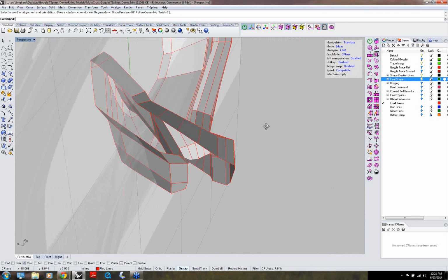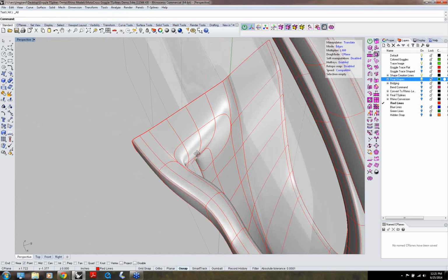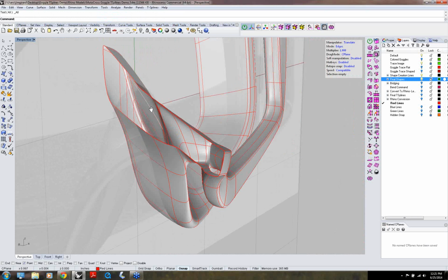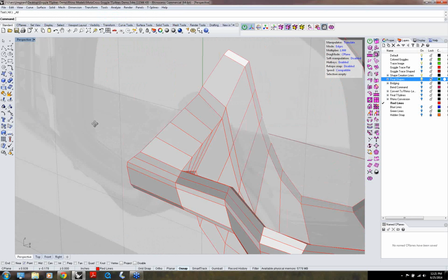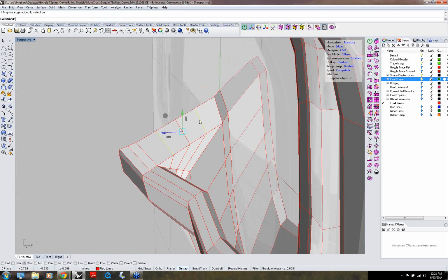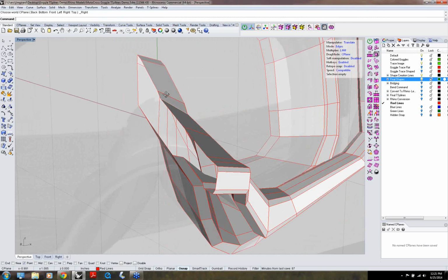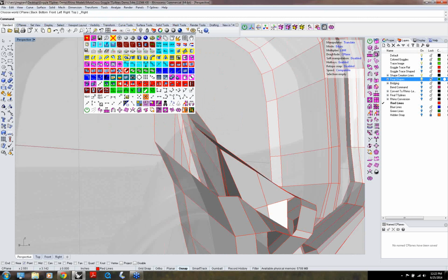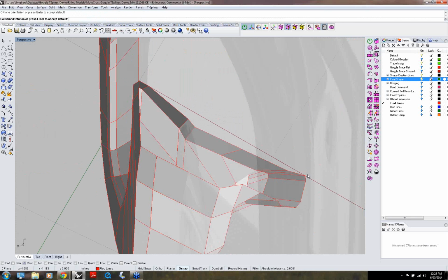surface. And if I hit my tab key, I can go now and you can see what a beautiful bridge that is. But I like to clean up my model as I go, so I'll share with you how that's done. So I go back to my box mode, and I say, now I've got overkill. I don't need these and these. Again, I like to eliminate detail that I don't need. And now I'll go to my right C-plane in Rhino. And then I'll pick 2 points. I'll pick that point and that point.